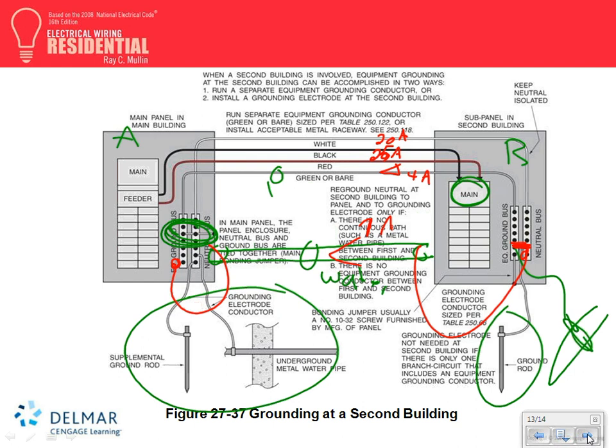Most of it will go through the neutral, but some of it, and it could be a substantial amount, guys, goes directly through the ground. So can somebody get electrocuted if they're working on the water pipe? Absolutely. You come over here and try to work on this water pipe, not knowing that there's 1 amp of current going through it at 120, and you zap somebody. Or it could be the phone line, guys. It could be any metallic object in between them.